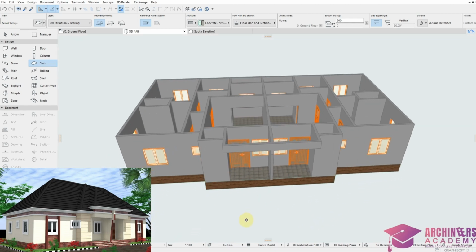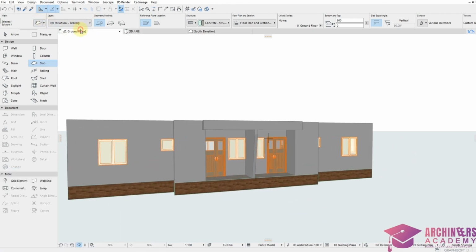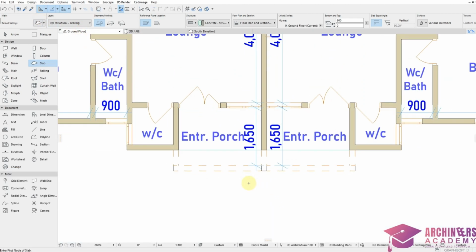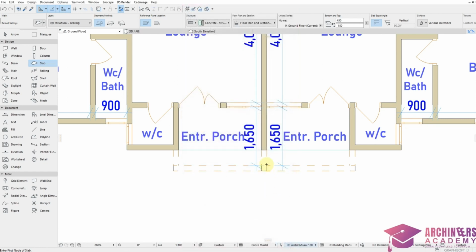Alright, but let's add our staircase, or rather the steps. Remember to easily add steps, make it of slab. The first step height should be 450. It's projecting downwards to minus 150. Okay, so place the step.